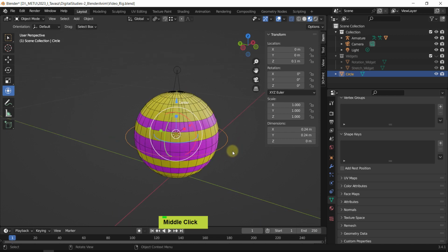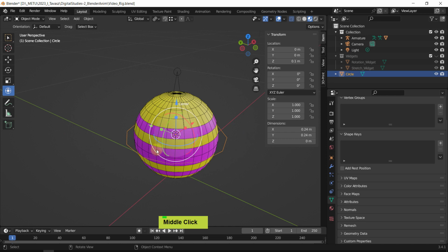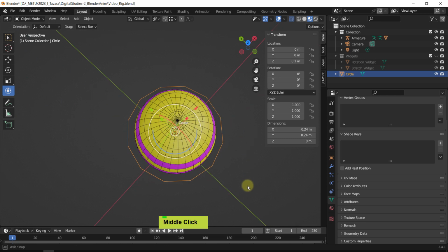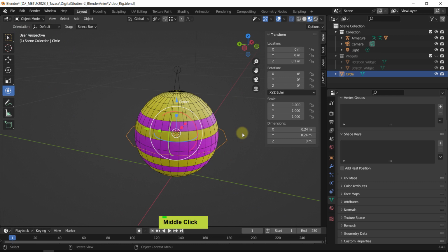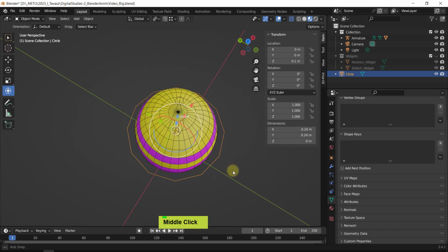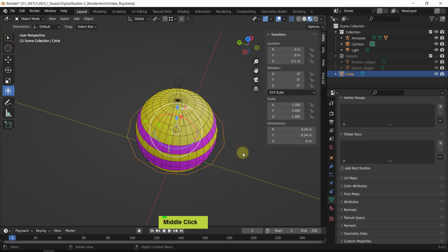Now, but before I do that, I will reduce the number of vertices a little bit lower, let me say 12, and that way it's a little bit jagged, so the silhouette is not that super smooth, and it's easier to recognize if it rotates and moves in the 3D space. You can add some handles, or you can make a few tricks here and there if you wish.